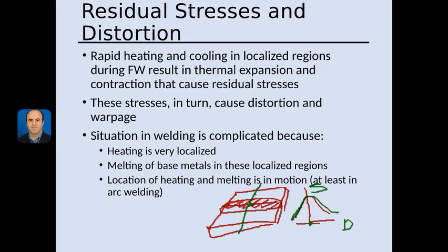And why does it happen? It happens because of the localized heating and localized cooling in the welding. Because we are heating this area, right?